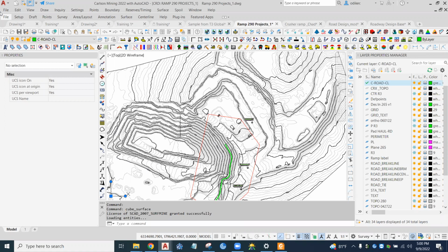Maybe that fill slope is sitting on a 3 or 4 to 1 from the top down to where it hits the existing ground. Well, they have to drain that pad, but they can't run the water down that slope. It's too steep, it would cut into that. So they have to figure out how to get that water down at a gentler slope.